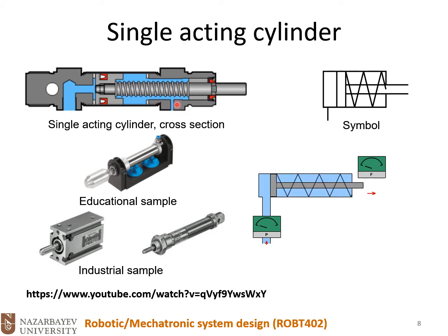So without this small vent here, the piston moves forward but will stop, because the pressure inside the right chamber will increase and then be equal to the left side. Once we are in equilibrium, the piston will stay somewhere between. So we need this vent to let the air move freely in and out from the atmosphere.